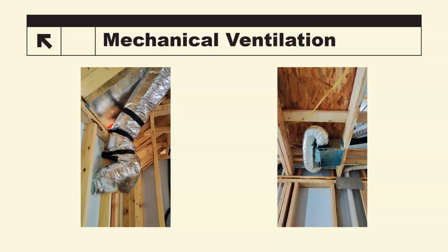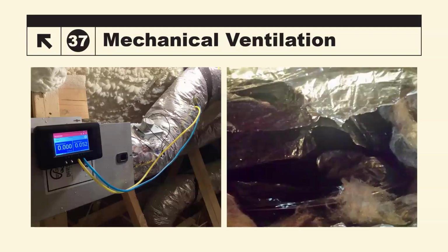I don't know the fix to this when you've got two different contractors installing one and the other, but they need to communicate, so that they're installing it for the best success of the airflow. It may take another foot, foot and a half, 2 foot of wiring, but really this should not be a wiring issue. It should be an airflow issue. So meaning the priority should be the airflow, not the wiring. So being installed this way is more than likely not going to pass.